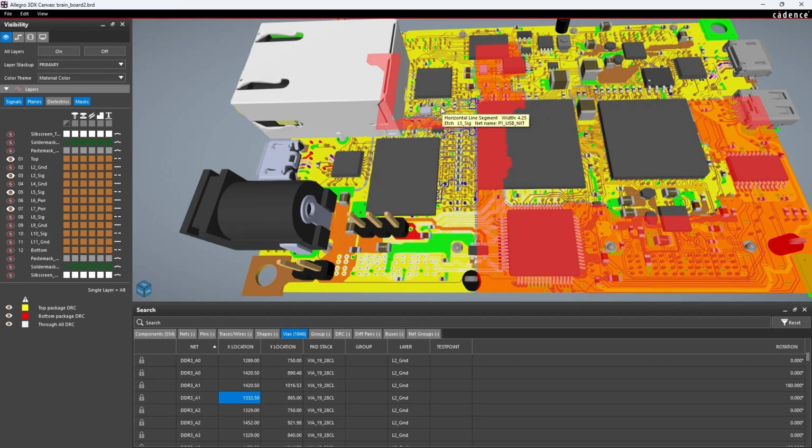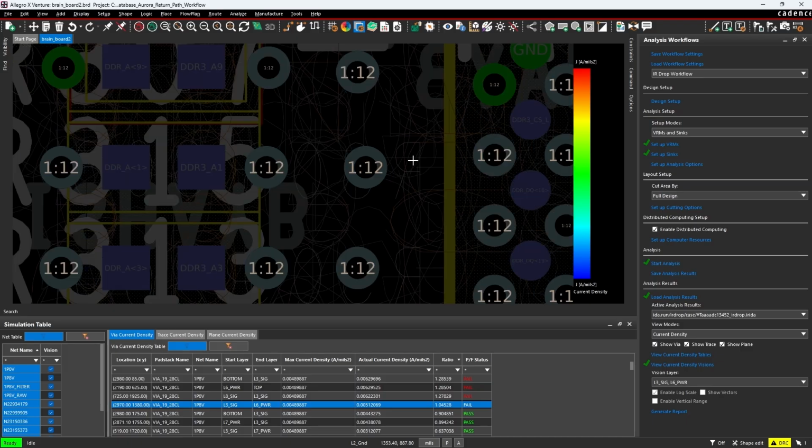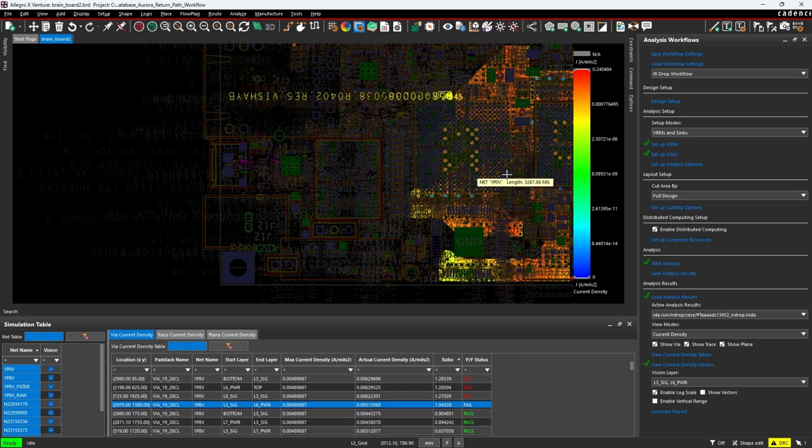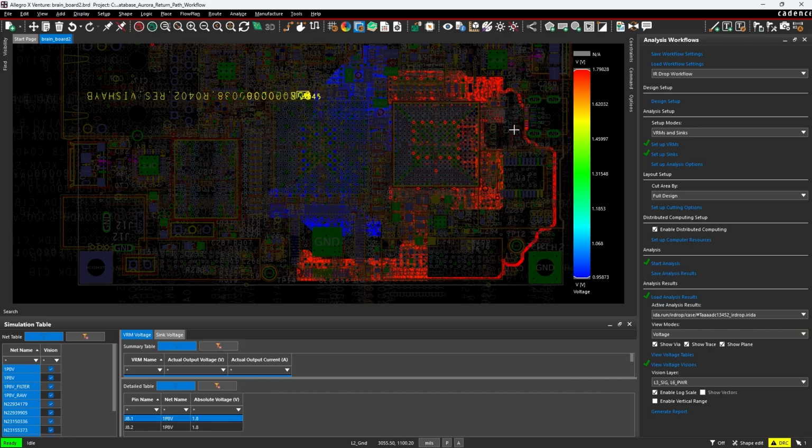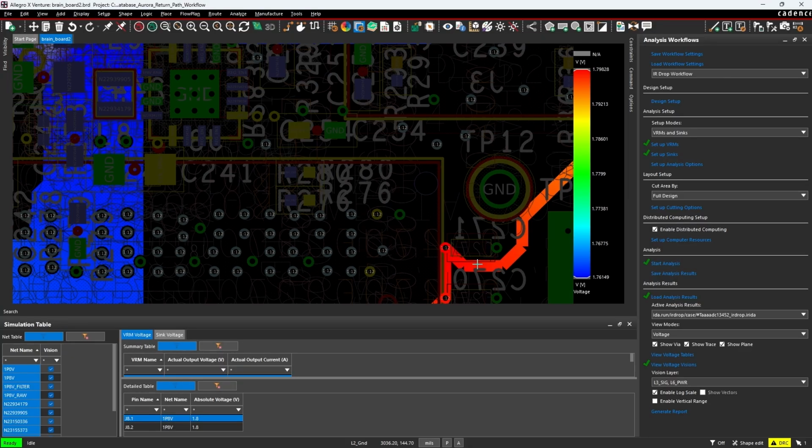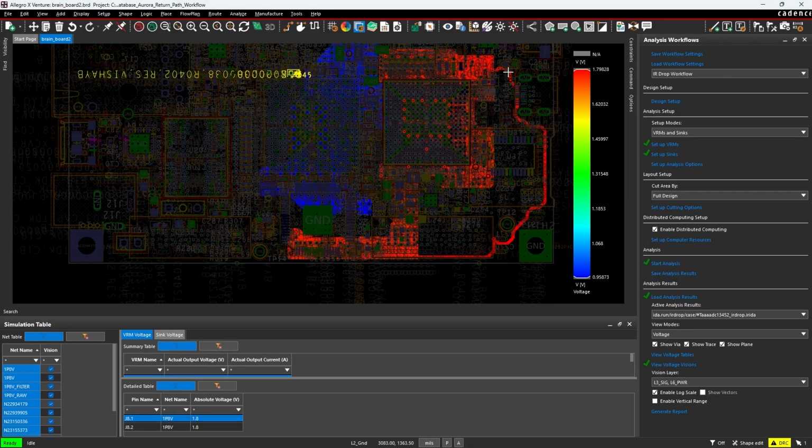You can also reposition your components to shorten the current path. Okay. If you want to reduce IR drop, maybe bring your components closer to each other where there is a problem. So if you have a major drop in voltage, you may want to look at and say, hey, looks like between this chip or this connector and the other connector, there is a large drop. Is there any way we can shorten this trace so that it doesn't have to go as far and we don't have as big a drop? Okay, that's another way to fix this as well. So these are layout changes you can make to reduce the IR drop without changing the schematic at all.